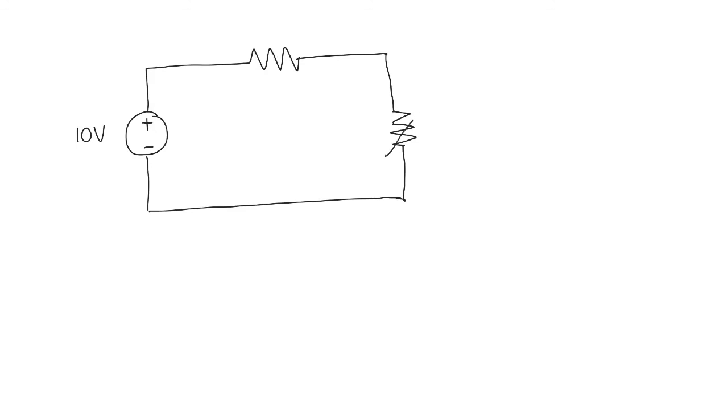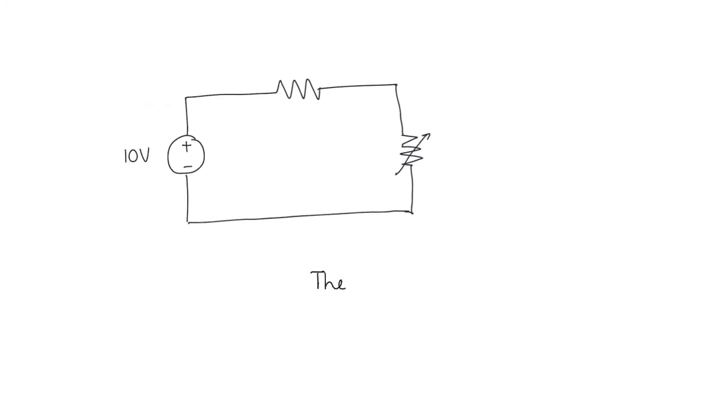And this resistor is changing, and let's say it changes in response to temperature, and that would be a sensor which is called a thermistor. A thermistor is basically a thermally sensitive resistor, or there are many other sensors which change their resistance based on the parameter that they are sensing. So for example, you could have force sensitive resistors that change their resistance as force is applied on it. You could have resistors that change their resistance depending on the humidity of the environment, and so on and so forth. So this resistance change can be used as sensors.